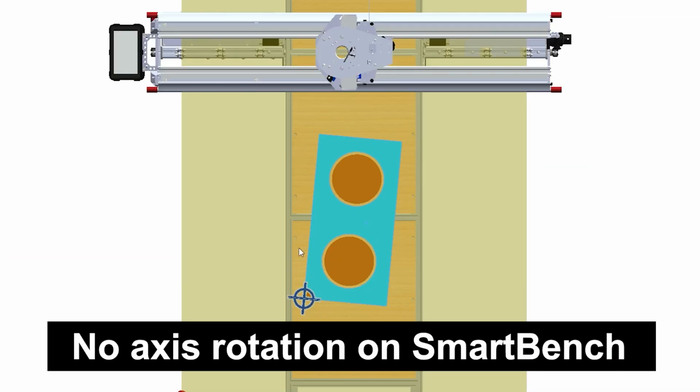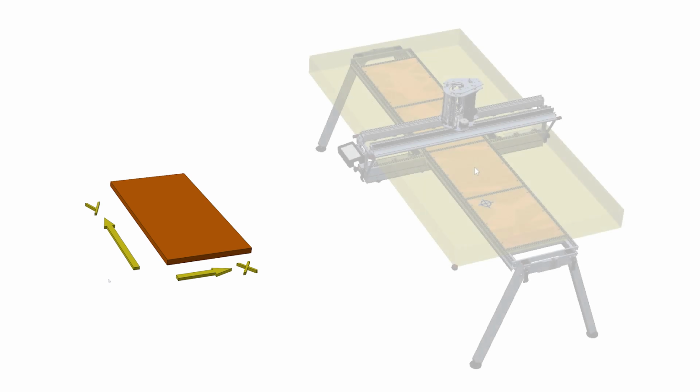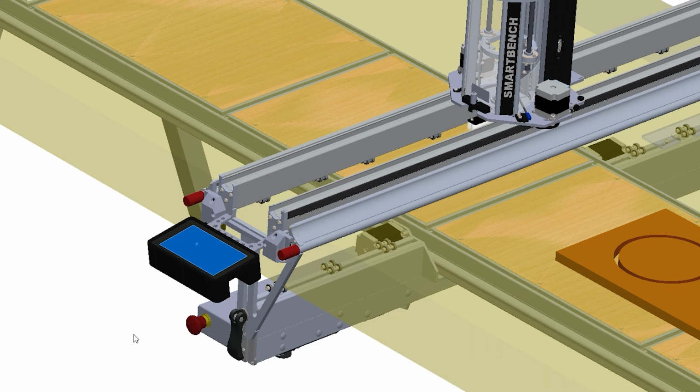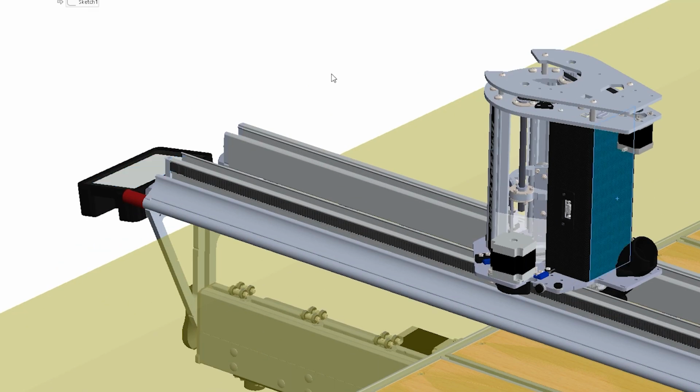Note that you cannot rotate the job file on SmartBench, so you have to design it along the axes which SmartBench uses, specifically the XY axes. The X-axis of the job will be parallel to the beam and the Y-axis will be parallel to the bench. And finally, Datums get saved, so your setup won't get lost between power cycles. The job file Datums will live safely in the job files, and SmartBench saves its working datum in the Z-head electronics.